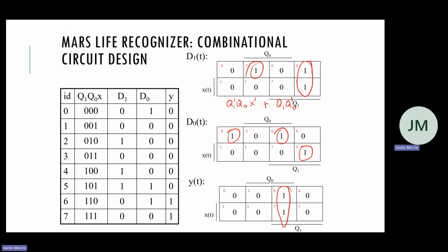Is the way that the X and the Q's are arranged around the K-map significant, or is that just another way to write it? Yeah, so basically on the top here, we have Q1, Q0, and X. Sometimes it'll be drawn like this. That just means that Q0 is 1 here. And where the line isn't drawn over, that's where Q0 is 0.